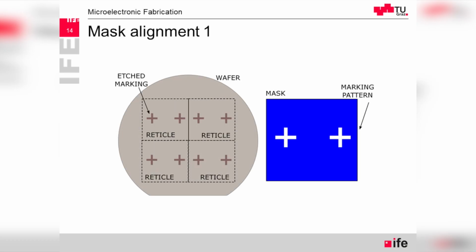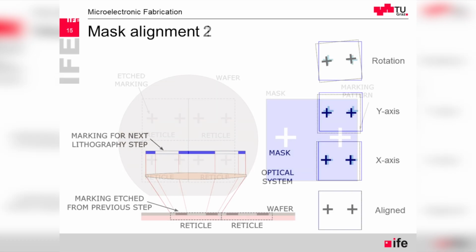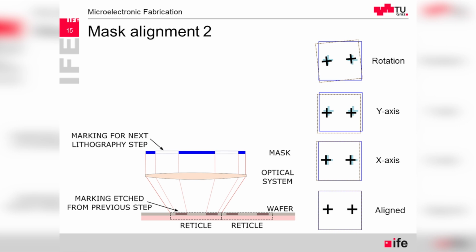For the photolithography process alone, we have this set of masks. One more challenge behind the processing of silicon wafers is the alignment of the masks. There are special markers for alignment. They are maybe no longer looking like crosses, but cone shapes. And again, there is a science of optics and mechanical engineering to be precise.